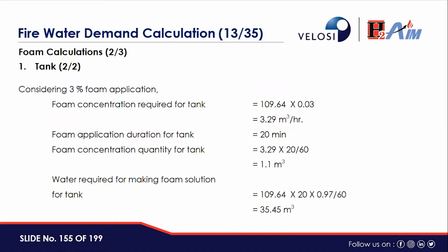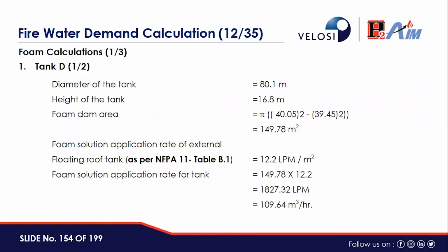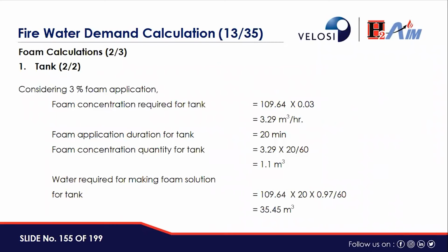By considering 3% foam application, the foam concentrate requirement for the tank will be this foam solution application rate of the tank into 3% foam application, and the foam application duration is 20 minutes. So the foam concentrate quantity for the tank will be this foam concentrate required for tank multiplied by the foam application duration, converting into hours. Water required for making a foam solution is 35.45 cubic meter.